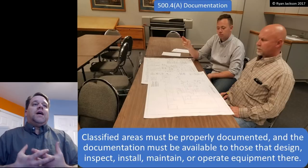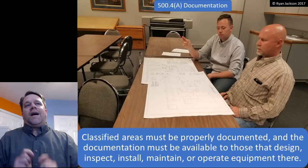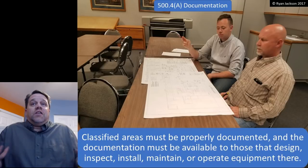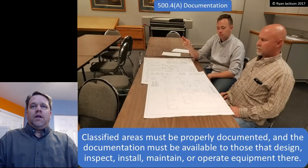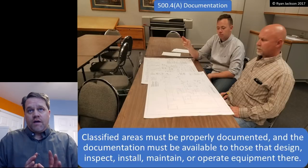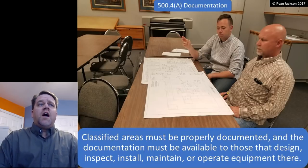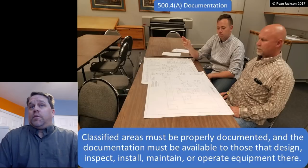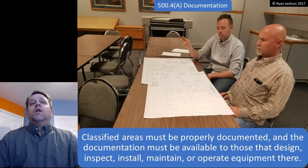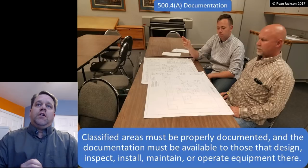If I don't have that information, I can't inspect it. And if I don't have that information, I can't install in that area. So areas have to be properly documented, and we've got to have that documentation available to people. So here in the photograph, we've got area classification drawings. I required that before a permit was issued. At facilities, I think that you deserve and you have to have the classified area documented.